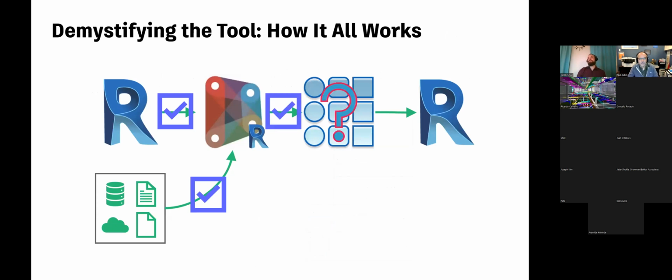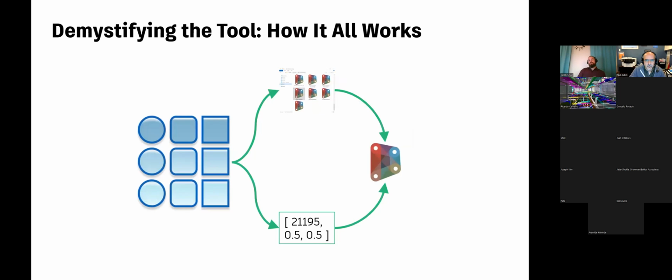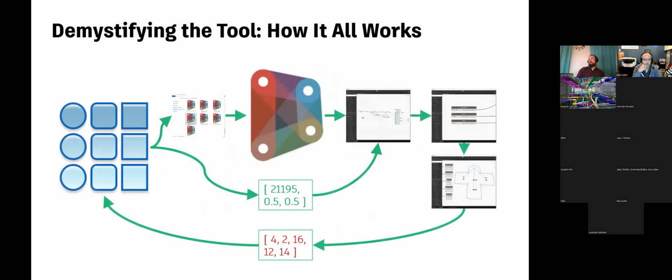What's this next bit? What actually happens when we get into generative design? Well, generative design, effectively, is a server that's going to spin up an instance of Dynamo by sending to a headless version of Dynamo that you don't see a copy of your Dynamo graph and a series of input values. And that all gets sent out to Dynamo Sandbox. So we're in Sandbox. We don't have any access to the Revit API, the Civil 3D API, the Forma API, or the AutoCAD API. So there are some limits to what we have to do in order to work with that data. But once we get that data in, that headless version of Dynamo is going to open up our graph, set our input values, get results, and send those results back to generative design.